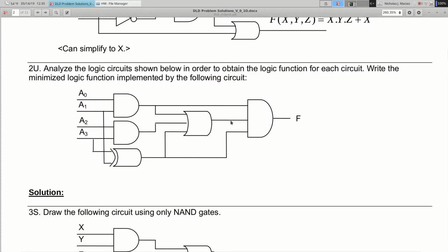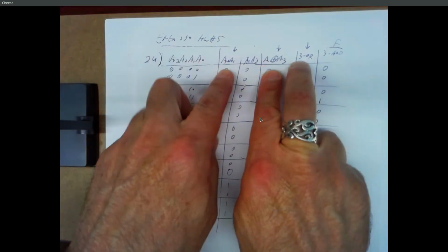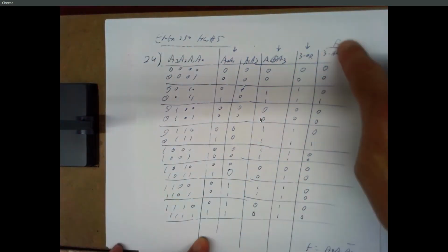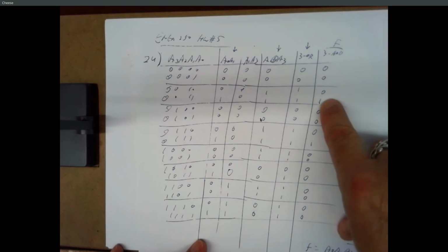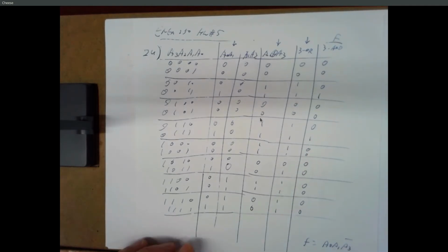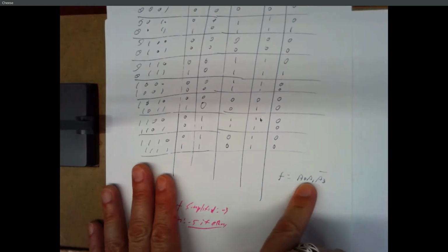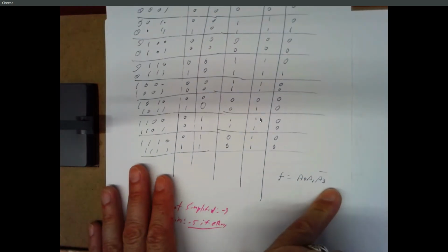And then you take that first column, the third column, and the fourth column, you AND those together. So now I just look at these three columns and AND them together, and I find a 1 in exactly 2 spots. Term 3 and 7. And if you make yourself a Kmap, you can simplify it one step, and so F will turn out to be A0, A1, A3 bar.